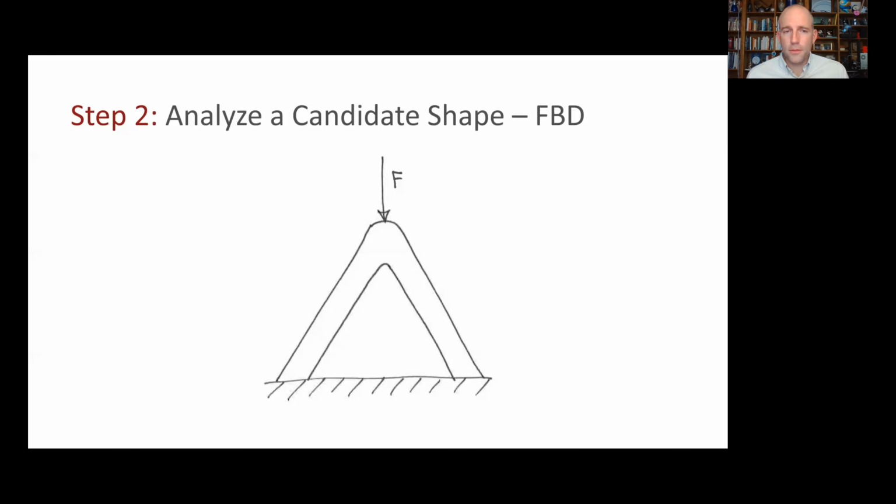All right, so maybe what you saw as you tried to develop your free body diagram is that because these legs are glued to the ground with magic glue, we have all possible forces and moments at those reaction points. And so our problem is statically indeterminate. This is something we run into very commonly in these mechanical design problems.